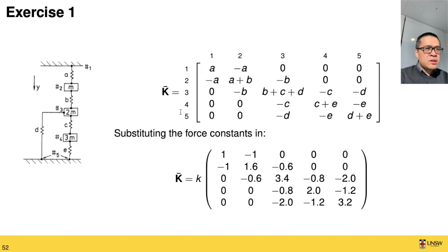For the non-diagonal element, or the off-diagonal element, okay, if it connects two nodes that are linked by a spring, then the value is the negative of the spring constant. If the two nodes are not connected in any way, then you give a value of 0. So to check that, for example, this matrix element links together nodes 1 and 2. Nodes 1 and 2 that are linked together is minus A. Right? The spring constant is A, so this matrix element here is minus A.